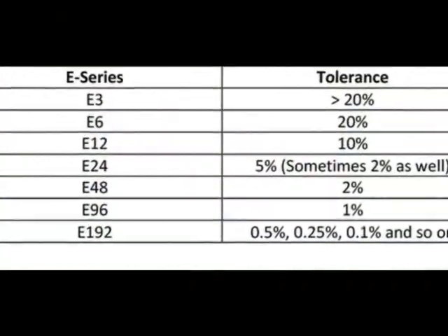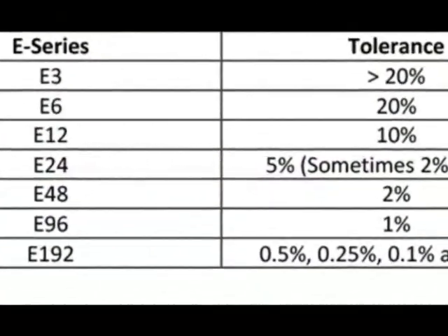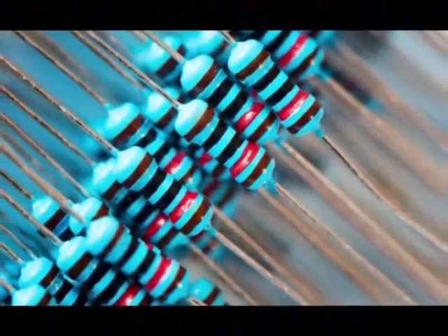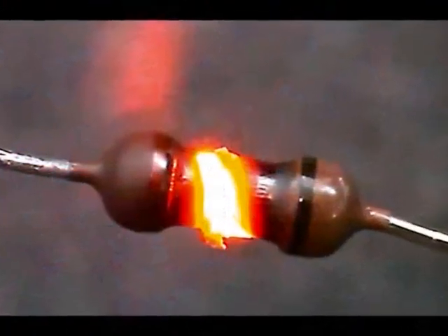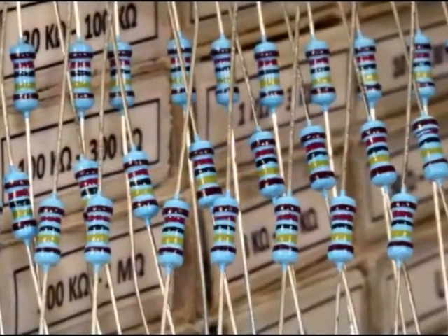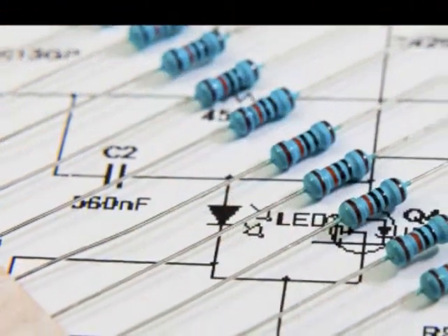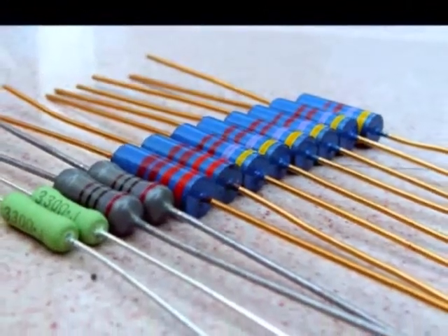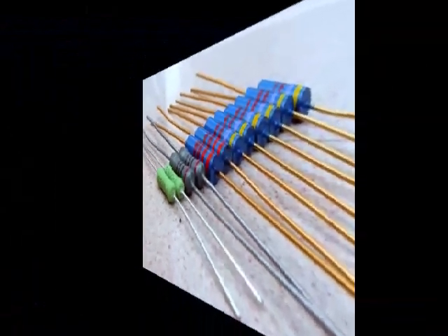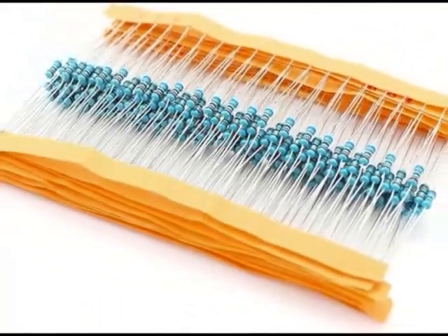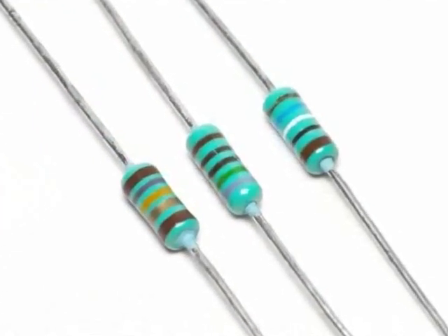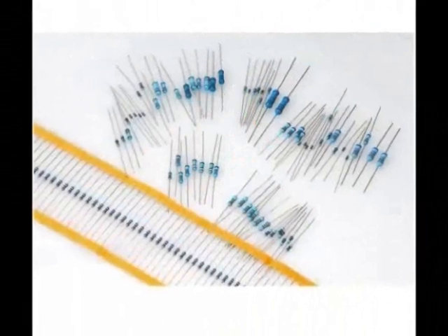These types of resistors have good thermal stability and low noise. The ability to withstand high voltage in metal film resistors is high, but the ability to withstand impulse current is low. Metal film resistors are named with the prefix MFR, e.g. MFR 100 Ω, and the CF prefix is used for carbon types.